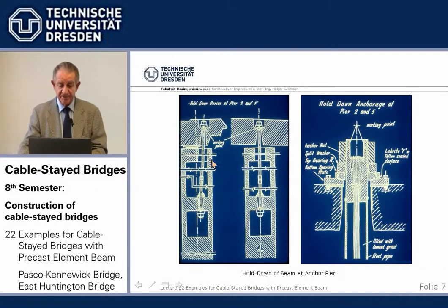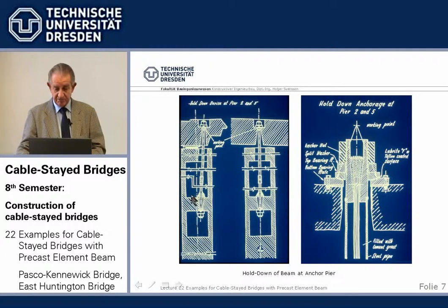Now, we have used post-tensioning strands to stress the beam down. There's a bearing which is always under pressure. Otherwise, if you don't have that, you may have uplift or downlift forces depending where the live load is. So we have always compression in the bearing because we stress it down.